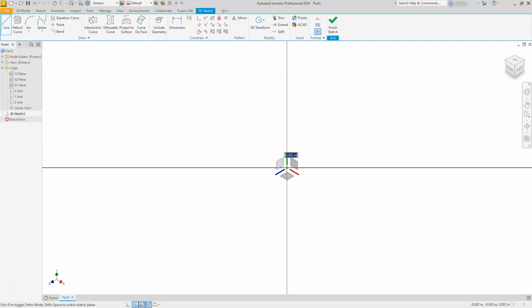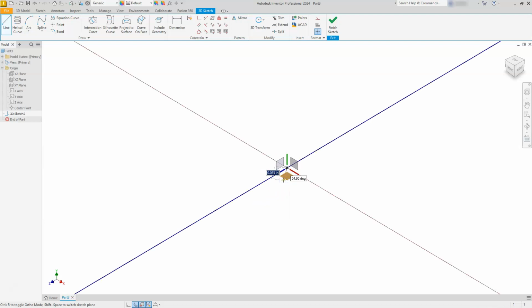And then the next thing you need to do is go ahead and define what plane you're going to create this on. Meaning, which one of these planes am I going to draw on? So I'm going to create this shape, and I'm going to draw on this plane here. So I'm going to select this plane. And then you're going to get these axes that show up. With these axes, you can go ahead and highlight and hover over them. And now you can see that this is going in the Z direction. If I rotate this direction, you can see next to my cursor it's saying X direction. So these lines are telling me that I'm parallel to the X direction or the Z direction on this plane. All right.